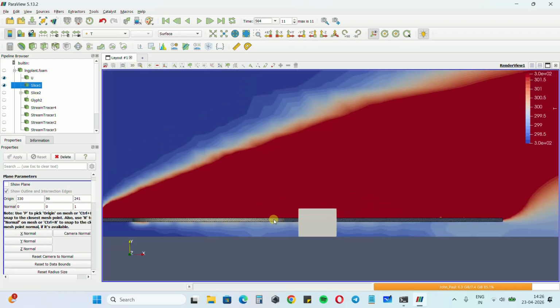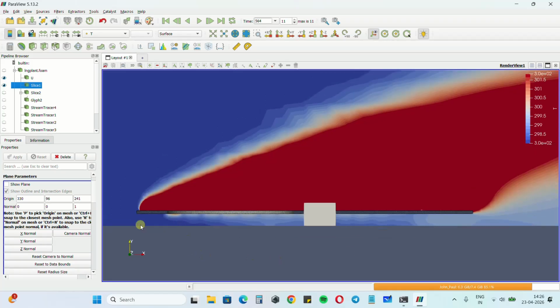Here you can clearly see that the minimum is 298, and apart from the first two heat exchangers over the leading edge, almost all the others' inlet region is affected by the exhaust temperature. So we need to somehow block the exhaust gases from reaching the inlet area.